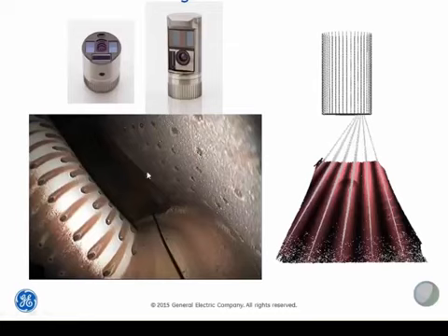Now, 3D phase measurement, unlike stereo, provides a high-quality full-screen image that is great for general inspection while also providing measurement capability on demand. So by eliminating tip changes, we make the inspections more efficient, and you don't have to worry about the problem of relocating an indication after withdrawing the probe to attach a measurement tip. So we find that for most 6.1mm diameter applications, our customers generally prefer to use 3D phase over 3D stereo.